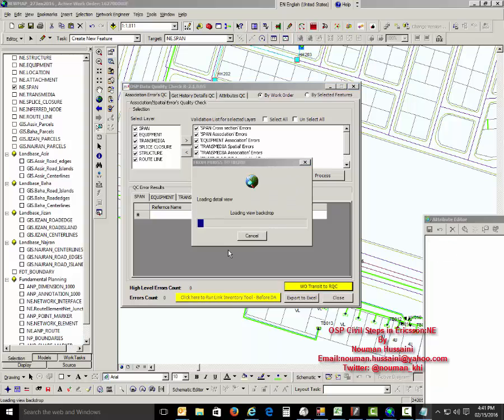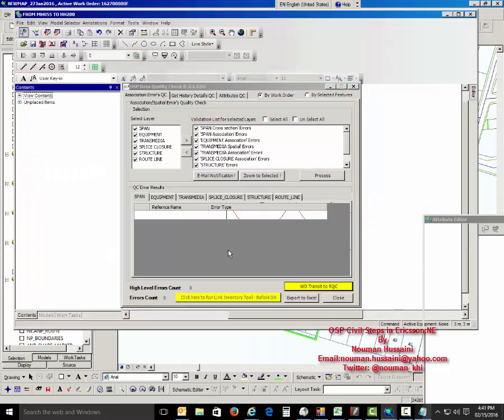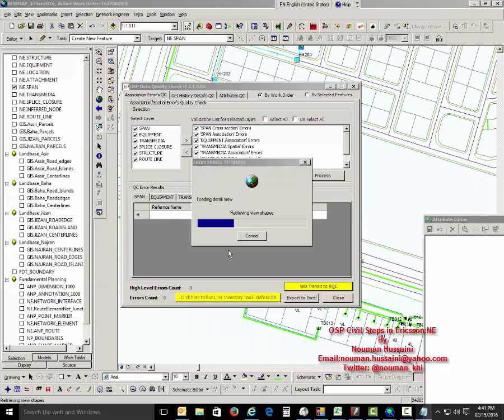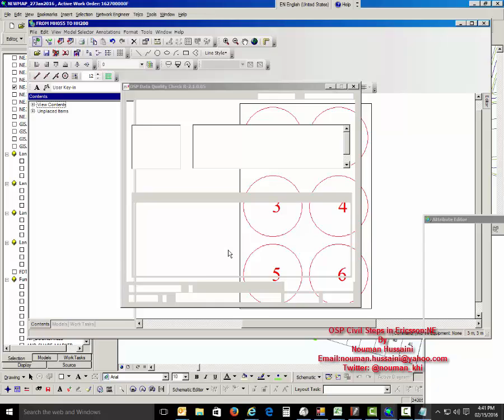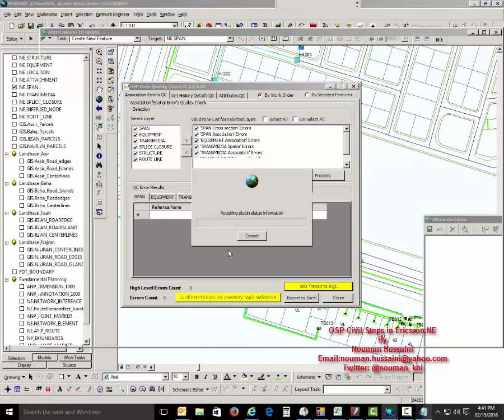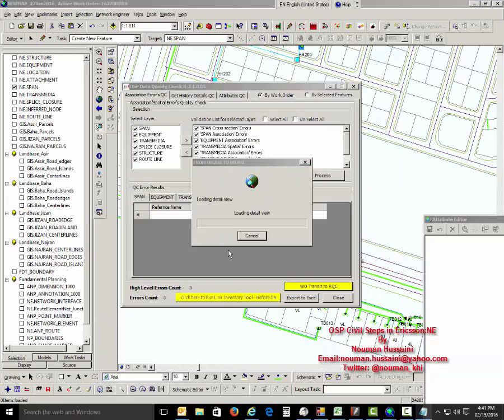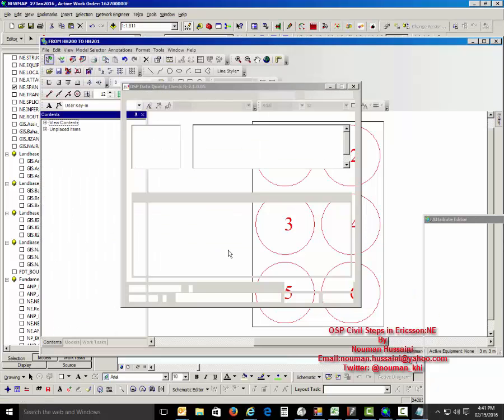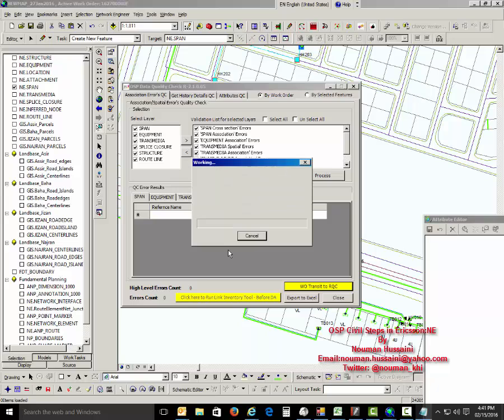Now I repeat all the steps. First step, create the work order. Use the go to XY button to locate your customer. From the Models tab, select the customer premises model, place that model on the desired GPS location, give it a user label.